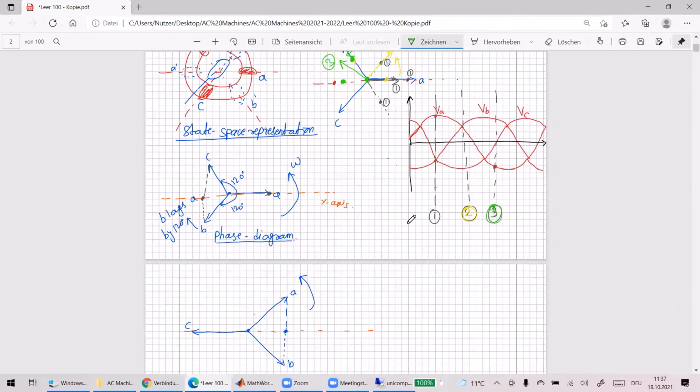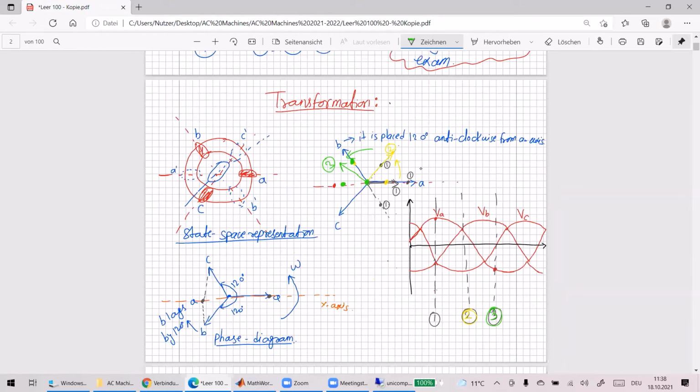In power systems, you might have heard of positive sequence, negative sequence, zero sequence, right? For the positive sequence, the rotation of the vector is anti-clockwise. And when we rotate in the other direction, clockwise, we call it a negative sequence. So in negative sequence, your A, B, and C sequences are reversed. This is for your positive sequence, so I can also write here positive sequence.